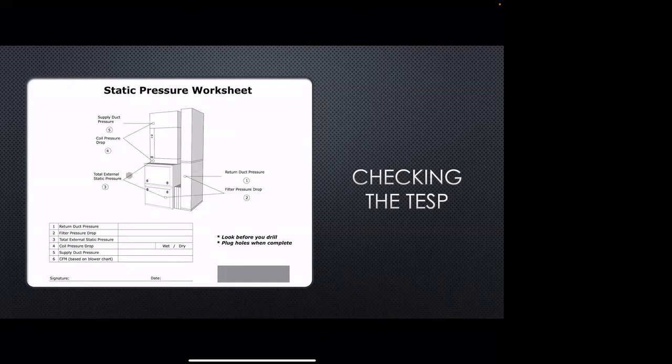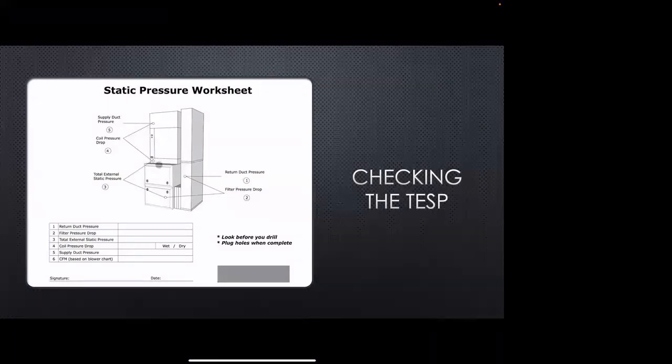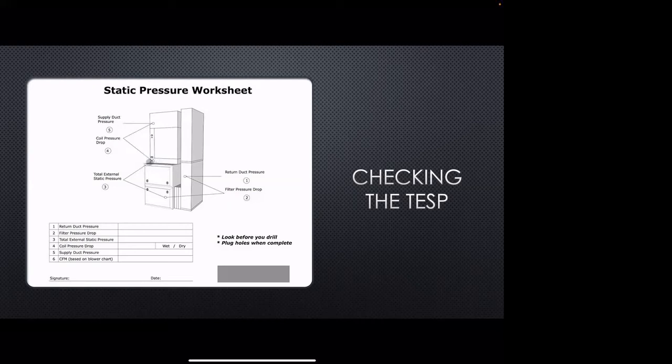So the third point that I like to check is before the coil. You can go in the high limit. If there's a riser box in between the furnace and the coil, go there. If you can still get up closer to the top of this past the heat exchanger, that's where most people are going to tell you to check it. I will agree with that.